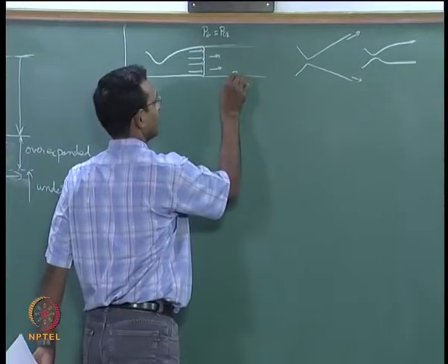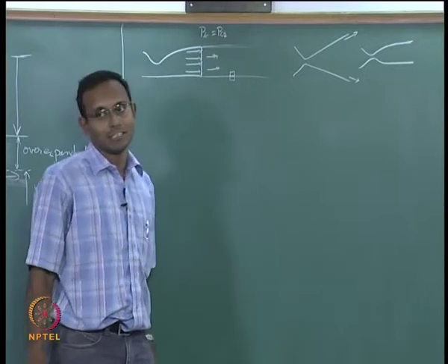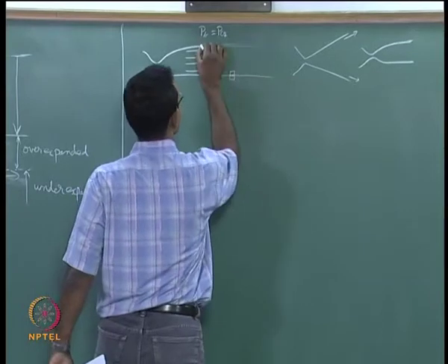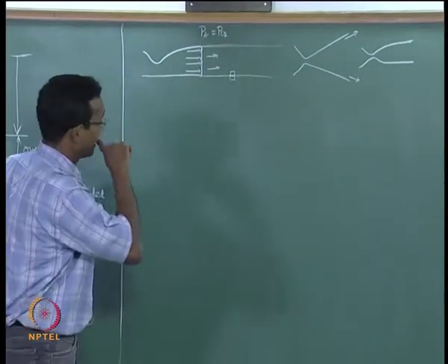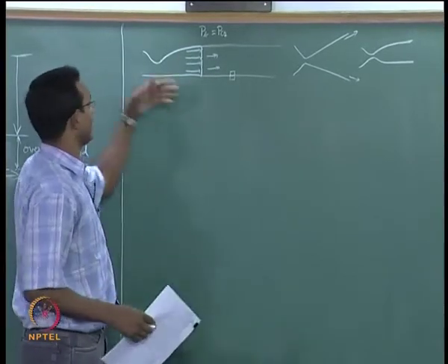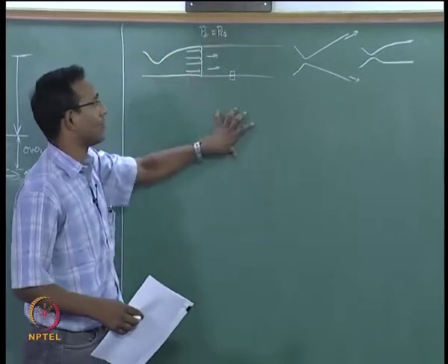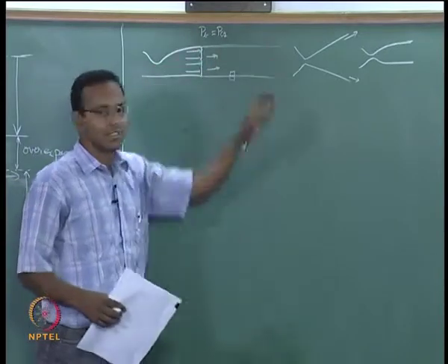Currently, we are going to say there is zero shear stress. We are going to assume inviscid flow, okay, because of which this jet will just be a straight jet without any question, no trouble. Life is very simple for the jet, it just has to keep going straight forever. Okay. Why is it just going straight? There was some region where there is high mass flow rate injected into some region where there is no flow. That region wherever there is higher mass flow will just keep moving like that.